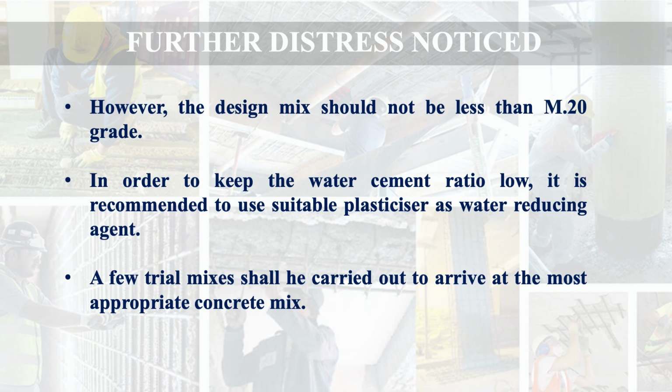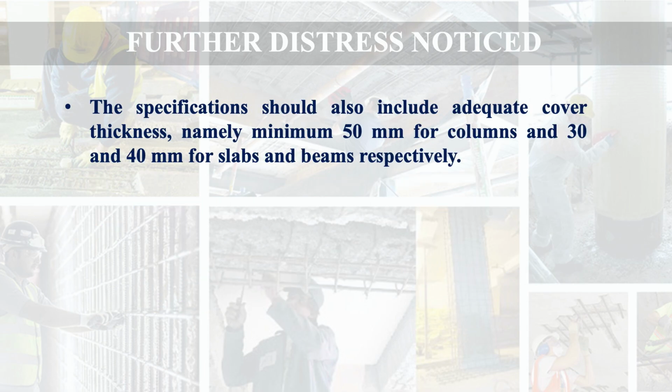A few trial mixes shall be carried out to arrive at the most appropriate concrete mix. The specifications should also include adequate cover thickness, namely minimum 50 mm for columns and 30 mm and 40 mm for slabs and beams respectively.